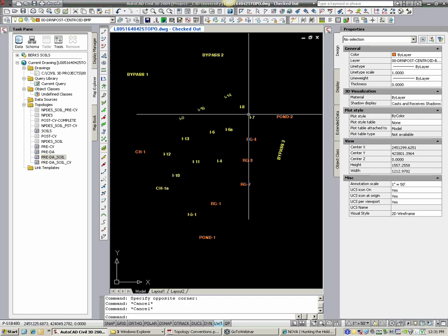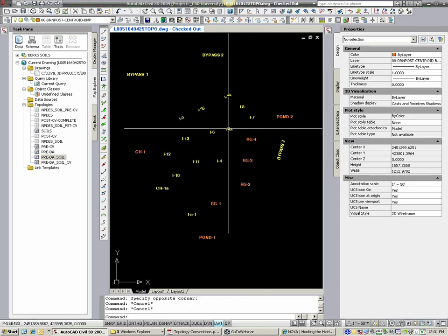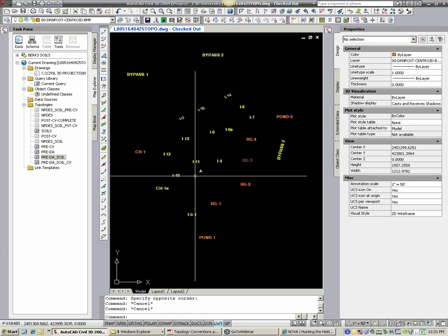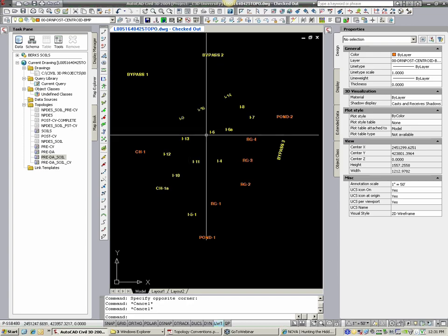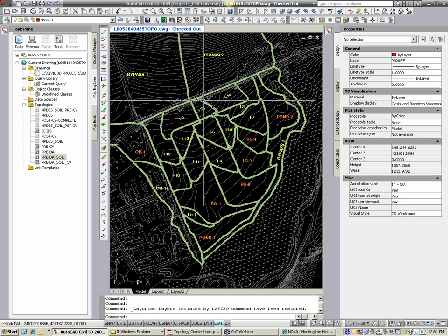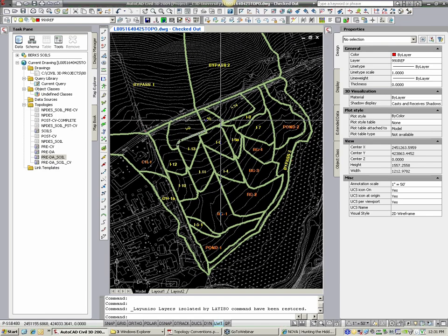Okay, so these inlets drain down, get into rain garden 4. Rain garden 4 goes into 3, and so on and so forth. And that's if you've ever done water quality analysis, you have to delineate that kind of stuff. What drainage areas go to what BMP, and even for just infiltration and stormwater management, you might need to do that as well.